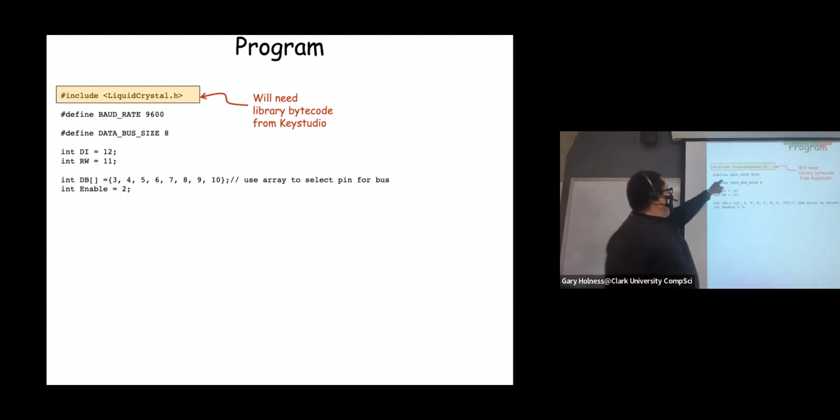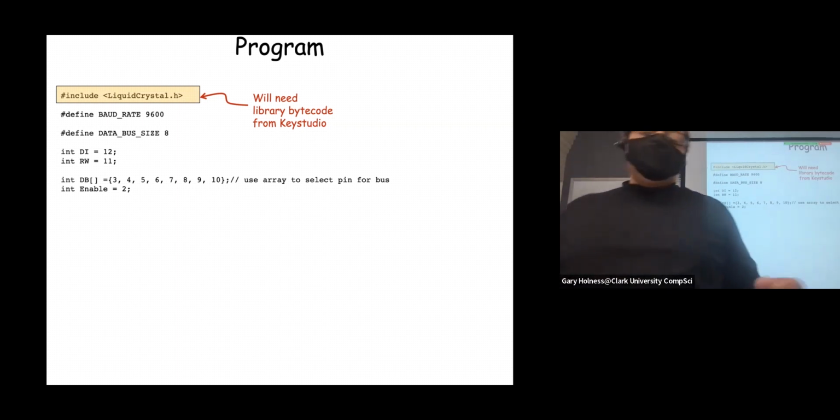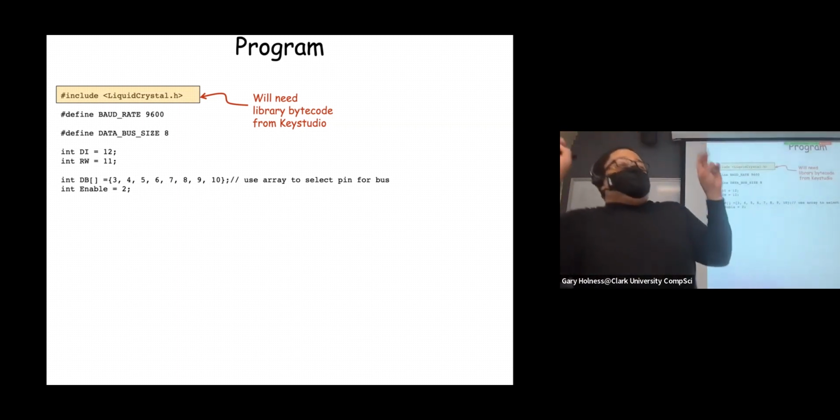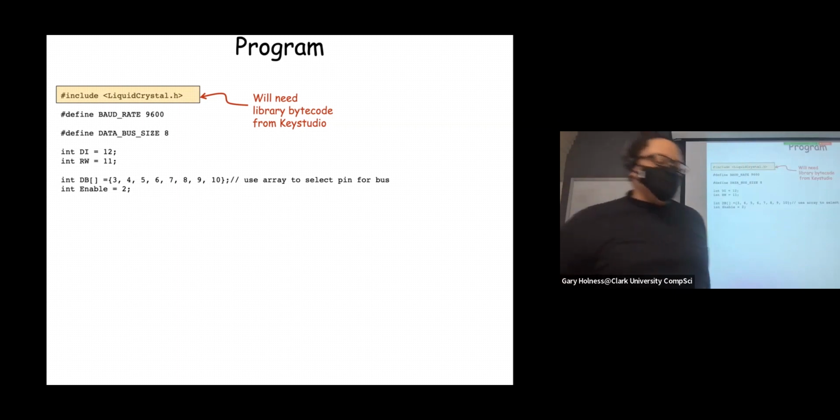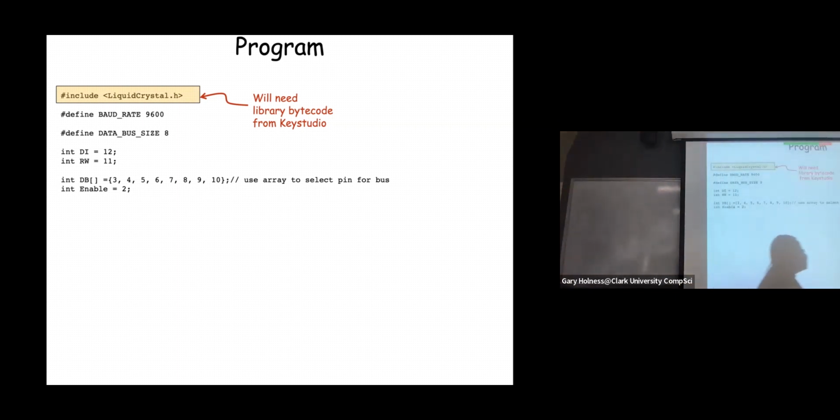Now you notice here, there are angle brackets, and angle brackets are reserved in C++. Well, this is not C++, it's a subset of C++. In Sketch, I'll say more correctly, these angle brackets mean it's a system library. Because you've installed it underneath your IDE, it's a part of the system library, in contrast with your own library, which is a header file, a .h file, like we saw in the alarm that you define, right? And so that's really, really important.